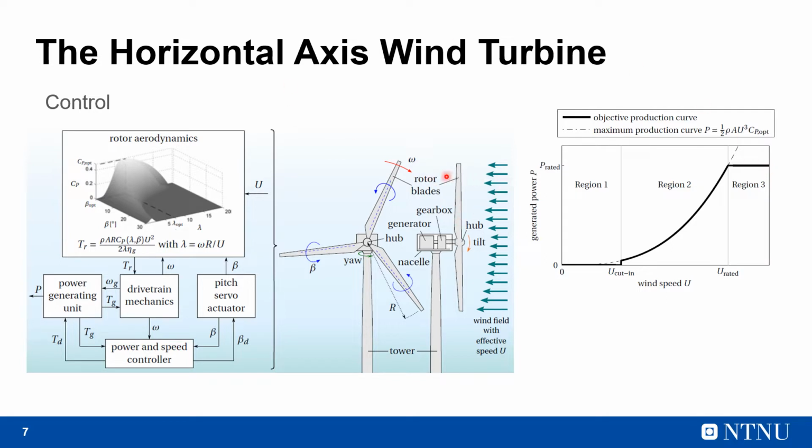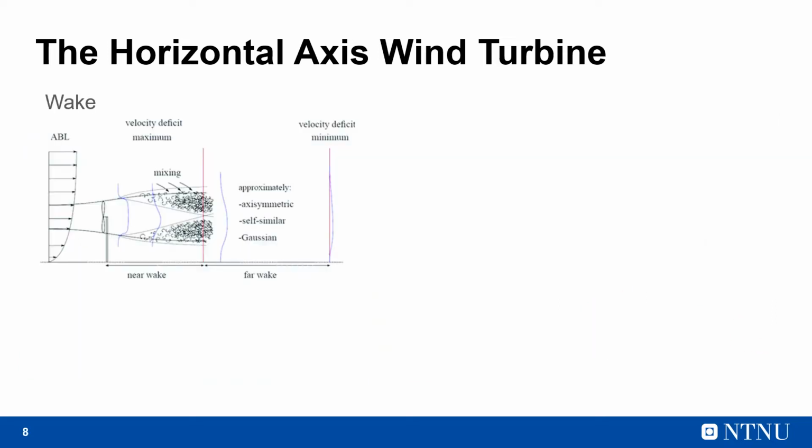Again, we see that when the wind interacts with the blades, rotor torque is developed, and this rotor torque is passed on to the generator through the drivetrain. The generator converts the kinetic energy of the wind into electrical energy and exerts the reactive generator torque. The generator torque can be set using the controller, and so can the blade pitch angles, and these are then tracked. The power curve shown is a simplified power curve. Usually there are transition regions, for example, to ensure a smooth startup, and control loops to limit fatigue and vibration.